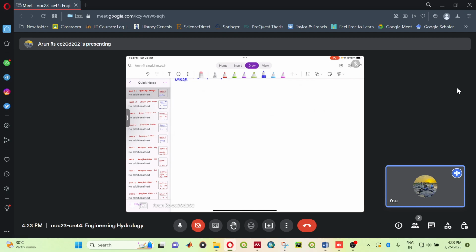Similarly, in the previous part A, we have done the same thing. So this is time in hours, this is rainfall in centimeters, and here we have the unit hydrograph coordinate, that is meter cube per second per centimeter. This is 1 hour unit hydrograph. And now we have the phi index. So this phi index will be changing. That's the only difference.